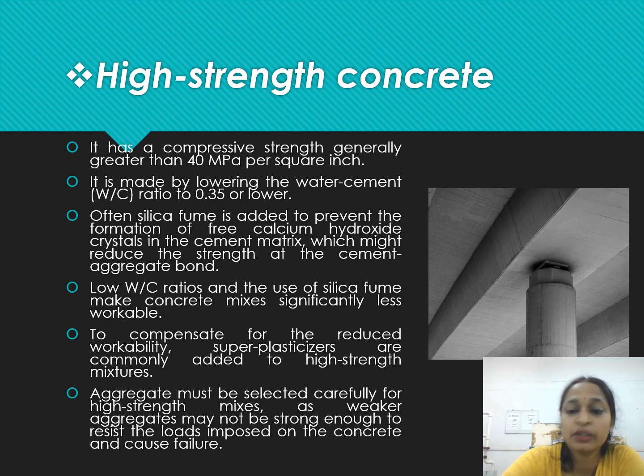Coming to high strength concrete. Now, what is this high strength concrete? There are two things. You have a concrete and you have cast it into cubes. Once you are done with it, you keep it dipped in water, that is curing, for 28 days. Then you find out its strength. Now the strength is very good. It is giving around 50 MPa or so, but gradually after some time it is reducing its strength.